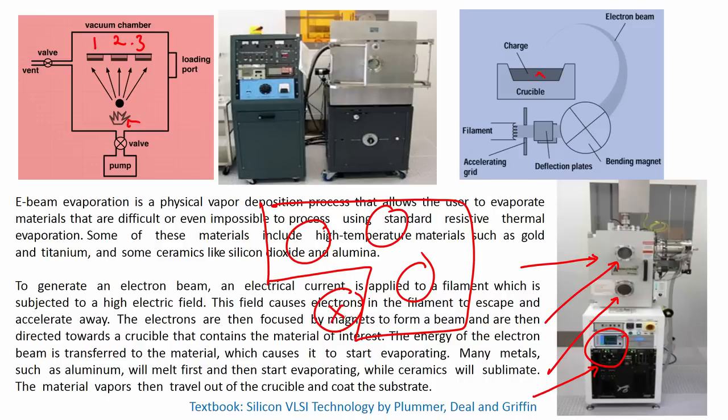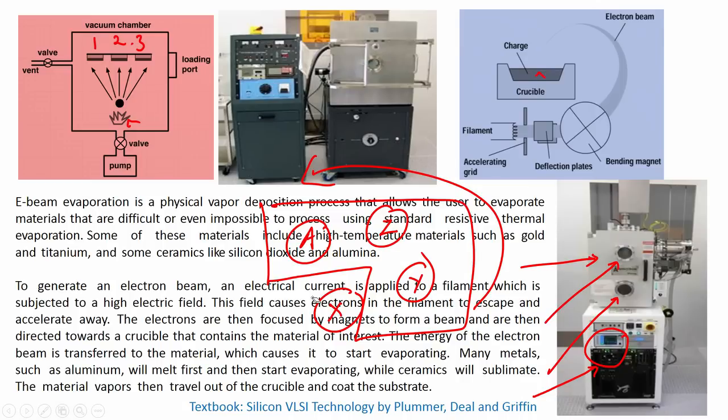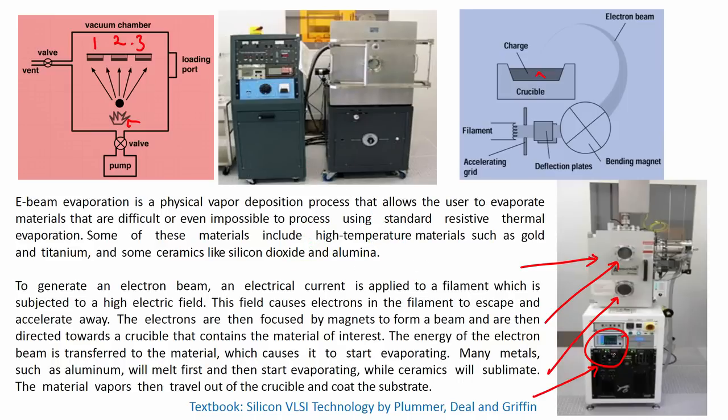That means you can deposit X material. If you are done depositing X material, then you have to turn this source holder, right, and this X will go to this position. Let us say initially it was like this, let us write X, Y, Z, A, alright, initially first step. Now, once I am done depositing the material which is in X, we have to deposit a material which is in A, alright, that is our process. Then in that case I will rotate the source in such a way that now my A will be here, my X will go here, Y will go here, Z will go here, right. So, for rotating the source, I have the source rotation facility which we can use using programming.